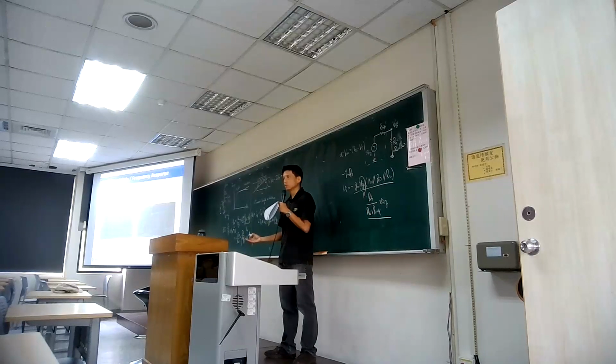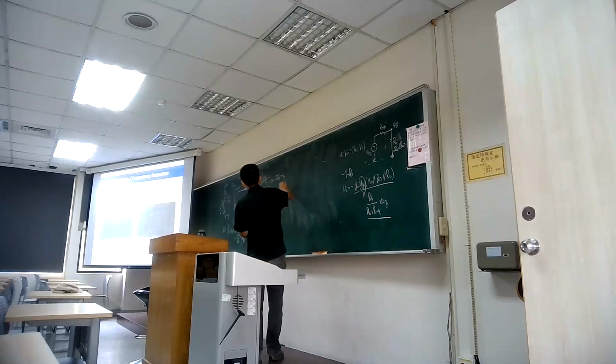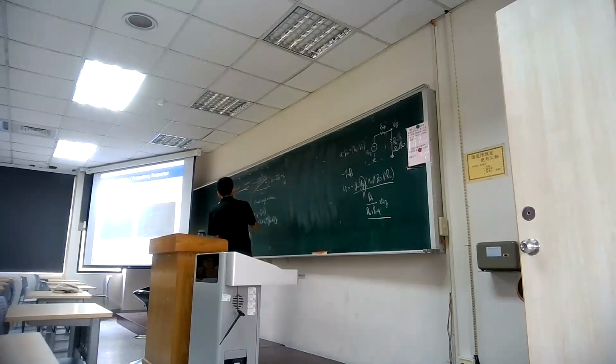If your resistance is larger, you get a slower response. If your capacitance is larger, you get a slower response. For the transistor, how do we avoid this or increase the response? So what is the transistor? Okay, maybe I just use this picture.